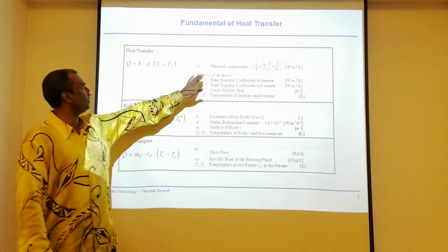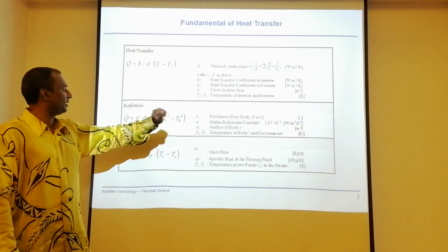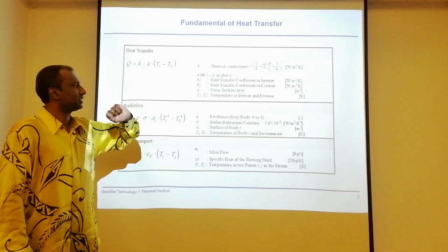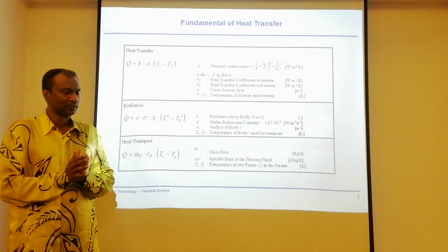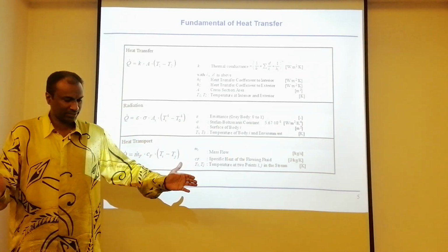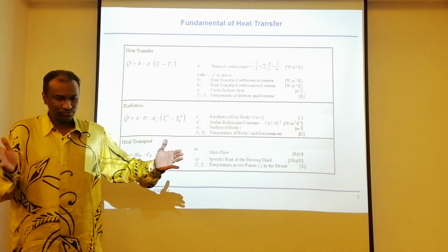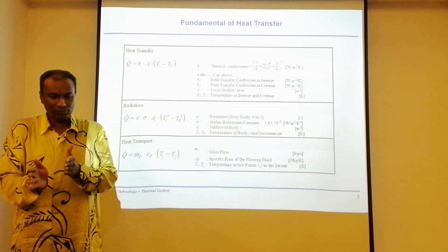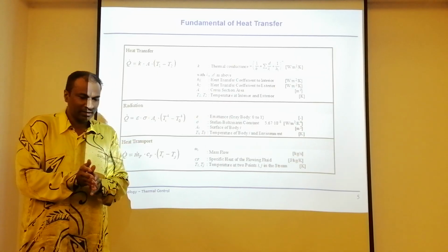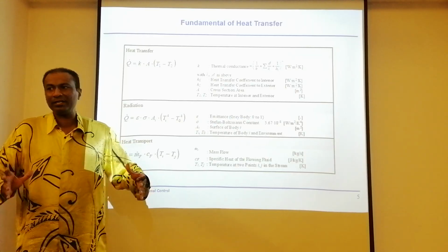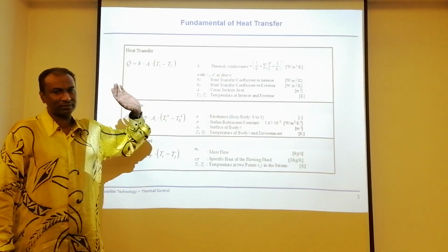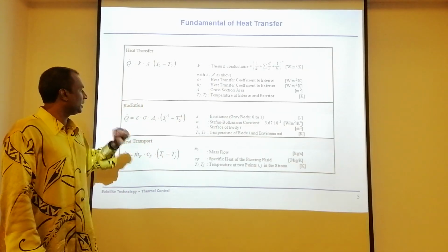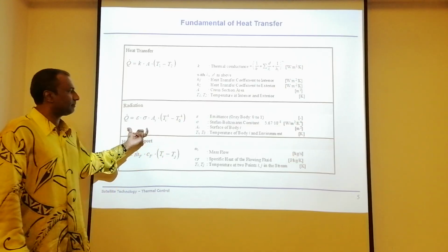So this can be easily done. And if you look at conductance here, it is not specific to only one material; you can have five different materials. Let's say A to B is aluminium and B to C is, let's say, steel. Technically you should be able to use this formula to calculate the actual heat transfer. And this is the most important that I've mentioned to you.